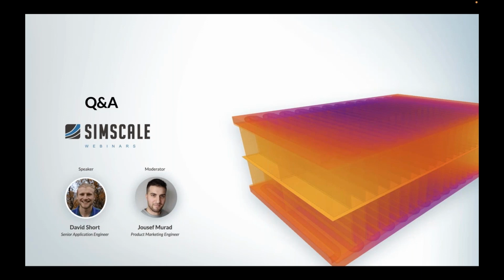So if you need to do some passive cooling or active cooling on, for example, LED devices, or battery packs that are actively cooled, this application here could also have been run using a conjugate heat transfer simulation where we simulate explicitly the fluid flow through those water cooling plates. I didn't bother doing that because I was only interested in the gap filler behavior, and I was happy approximating the cooling capacity of those water channels. But absolutely, using conjugate heat transfer simulations is where you want to go in terms of thermal management situations where you've got active and passive cooling applications.